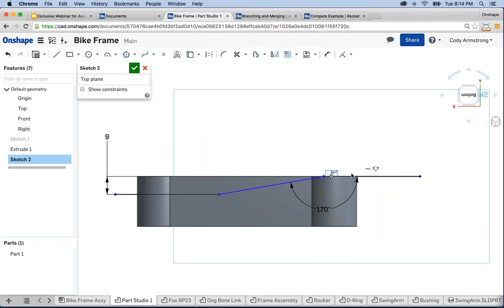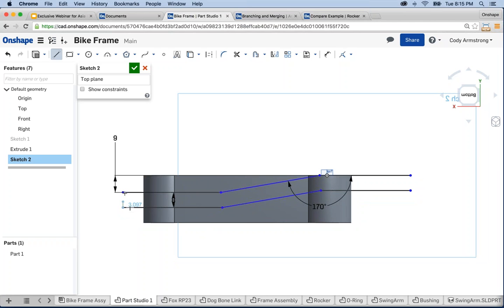I have 3 lines. And we have an offset tool. It's very easy to use. You can select your line and it offsets just the one entity. Okay. However, just a tip, if you select offset and you left click and drag, so rather than left clicking an individual line, you get the entire chain of geometry. So if you have 5 or 10 lines or arcs or whatever it may be, you can left click and drag and it will offset the entire chain. Right? So left click in space, we'll enter 8 for the offset, and we'll sketch in a few lines to